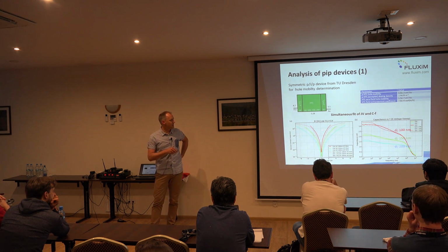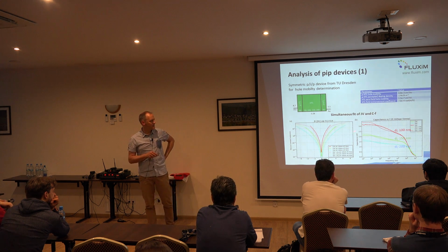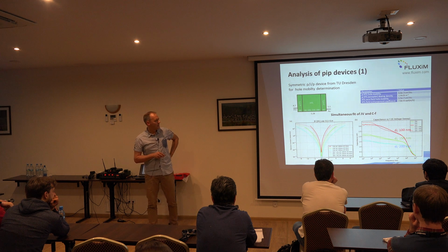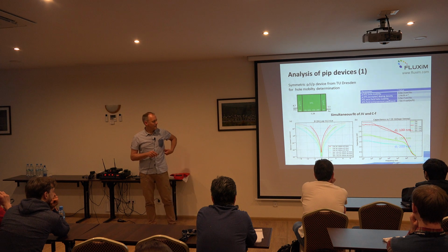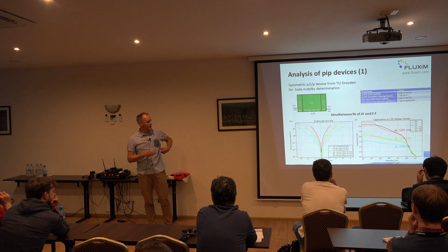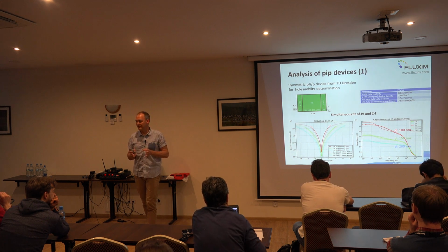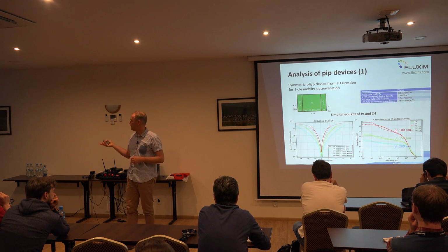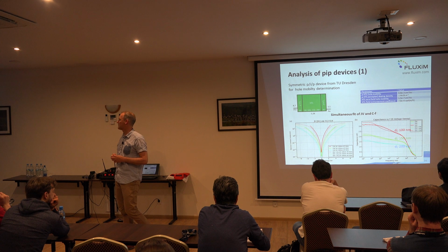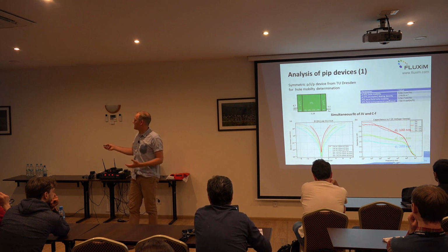And you see that the current voltage curves for the three devices, actually the thinnest thickness is not shown, but the other three thicknesses are shown. And then the capacitance frequency curves also. We have a kind of increase of capacitance at low frequency. And what you see here is a global fit. So we applied fit across all these 6 curves, 3 IV curves and 3 capacitance frequency curves, and tried to extract one set of model parameters.